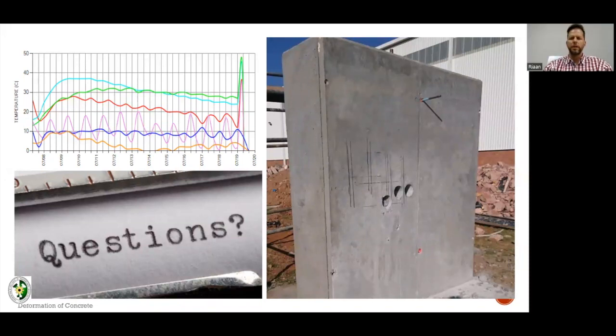Absolutely, yes. And not just for chloride attack per se. It is also beneficial for sulfate attack. It's also beneficial for anything that could or would want to get into your concrete, and that could possibly even be CO2, even carbonation. The denser your concrete matrix, the more durable the structure becomes.